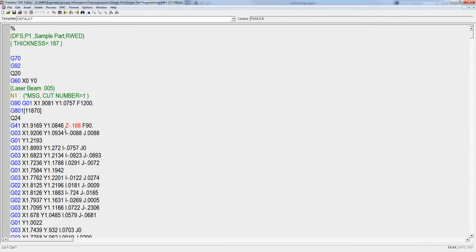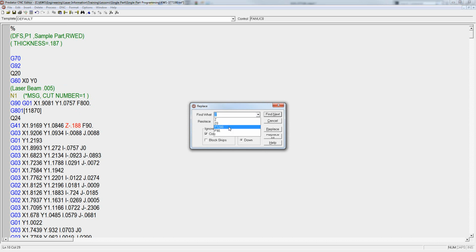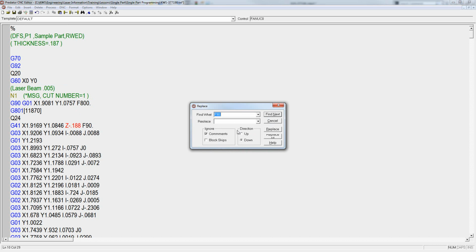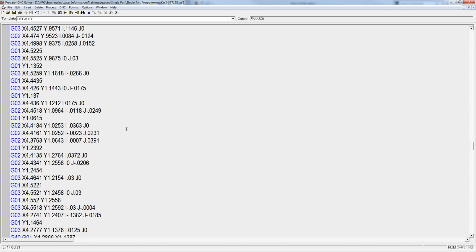And then our tool path shows up, so we'll do just like we did before. We'll change that to 800 for example, and then we'll just replace some of the information that we want to get rid of. Like we want to get rid of all the rest of the 1200s, we want to get rid of any 90s, just because we want to control it from the TechDB right here. And then we'll go ahead and just paste that. And there's no more Z's because we actually set our material thickness down and everything else is set the same.